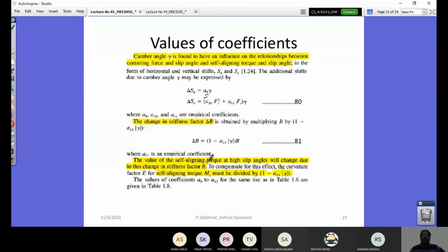You can just go through all this. If you have your table data of coefficients, you would be able to account for your pseudo camber and pseudo slip by horizontal and vertical shifts, and you would also have your normal load variation and its effect by means of different factors that appear in the magic formula.